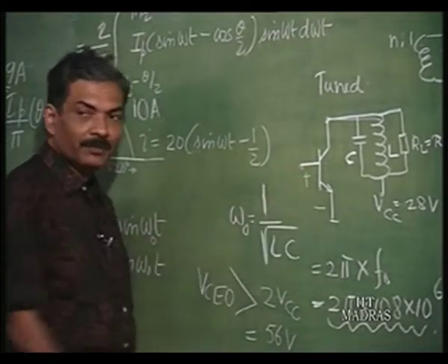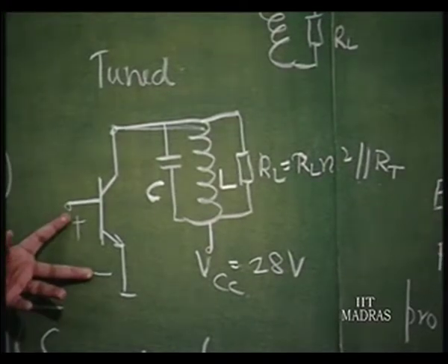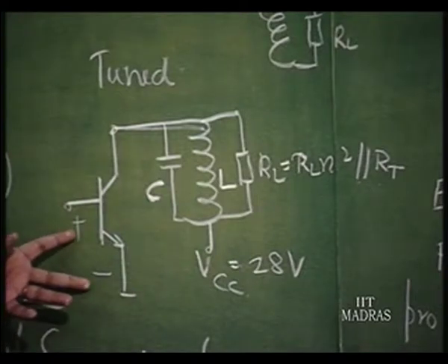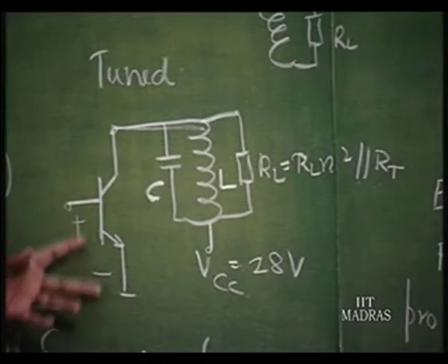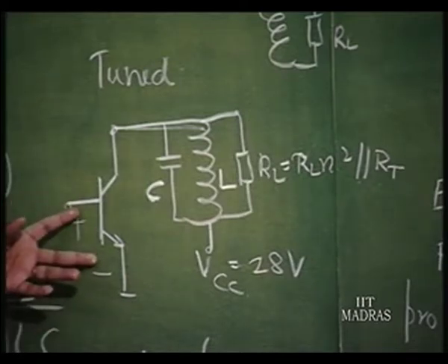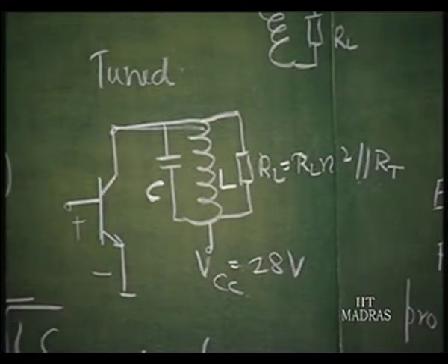As this is going to be a power transistor, the VBE when it starts conducting, for small signal transistors, is typically 0.6 to 0.7. Here, since the current of operation is of the order of amperes, strictly we can obtain the input characteristics of all these power transistors, and from that obtain the order of magnitude of VBE variation when this current is varying by this much. That is typically going to be between 1 and 1.5 volts. So, we will assume that it is going to be about 1 volt.